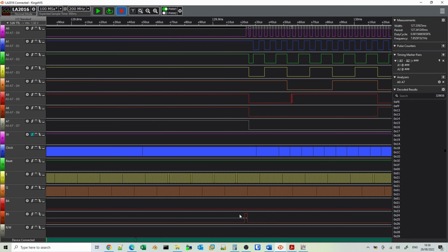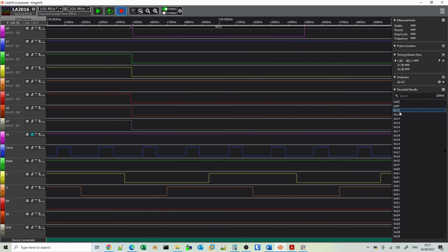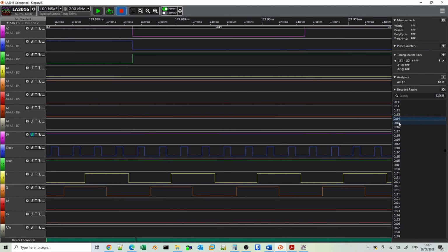You can see that the bus status has indicated that the reset is ending, and after this point in time the address bus starts to cycle, and we can see here that it was originally FEFF, which is where the reset vector is coming, and then starts with 12, 13, 14, 15, which, as we explained in the previous video, the no operation code is 12 hex, and so this is the value that will be provided for the reset vector.